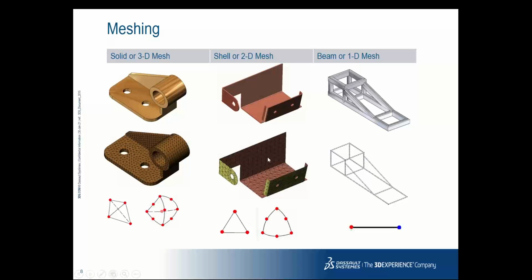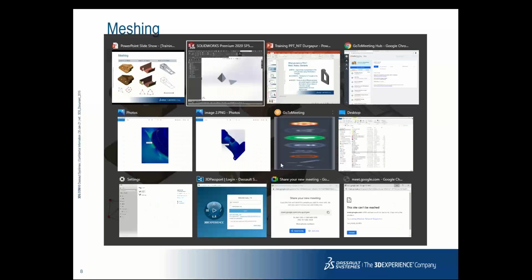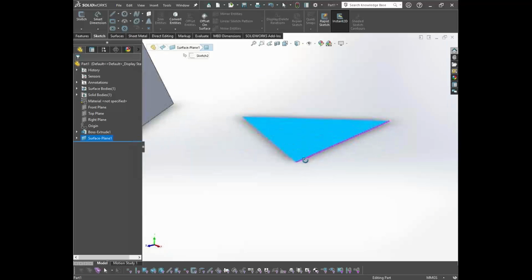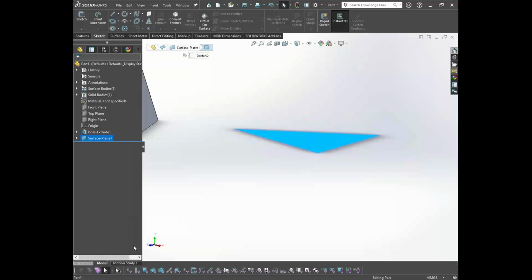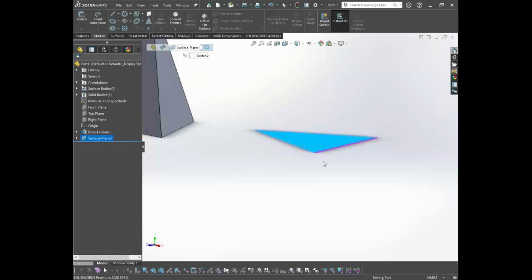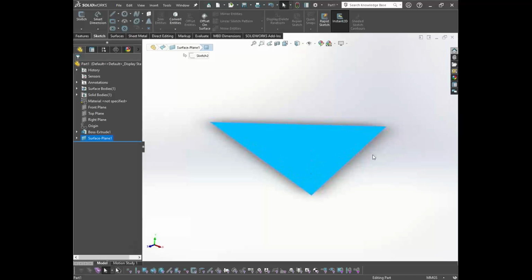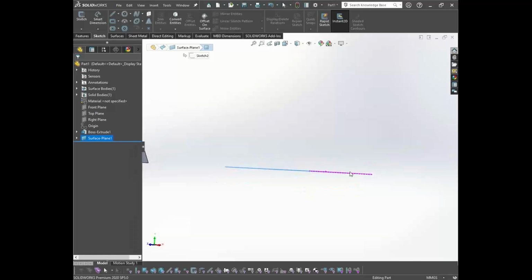What happens when I try to bend this particular sheet metal component, if you can imagine it? If I want to bend it with my bare hands, I am able to bend it, as the shell elements have 6 degrees of freedom. If I'm considering this particular problem, if I want to bend it, it can translate in the XYZ direction. There's no doubt about it, since it is free to move in space. Now, when I try to bend it and apply load, or press it with my fingers, with my thumbs, I can bend it in this particular y direction.